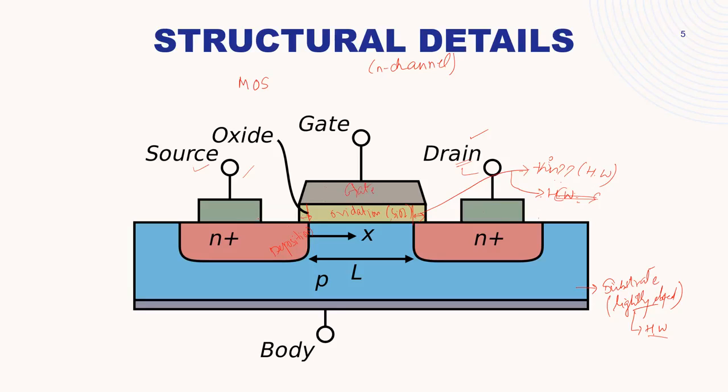So sometimes electrical contacts are not made again, and the gate also deposits here and here everywhere. Again, it is etched out, and the gate comes directly over the oxide top. And again, you can make electrical contacts to source, drain, and gate. Understood? This metal layer is acting as gate. So this device will have a metal layer on the top, the oxide layer in the middle, and the semiconductor structure at the bottom. Hence, it is called the MOSFET.